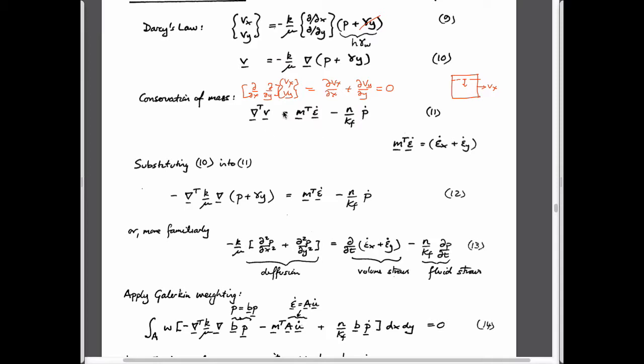And so we have two sources by which we can change that, and they operate in the opposite direction from each other. Physically, if volume in doesn't equal volume out, then that expression doesn't equal 0. There are two ways in which that can occur. The first term is if you take the control volume and you strain it, you squeeze it, and you don't allow any fluid pressure to rise in that system because it's open, the amount of volume of fluid that has to come out is the change in volume of that system.